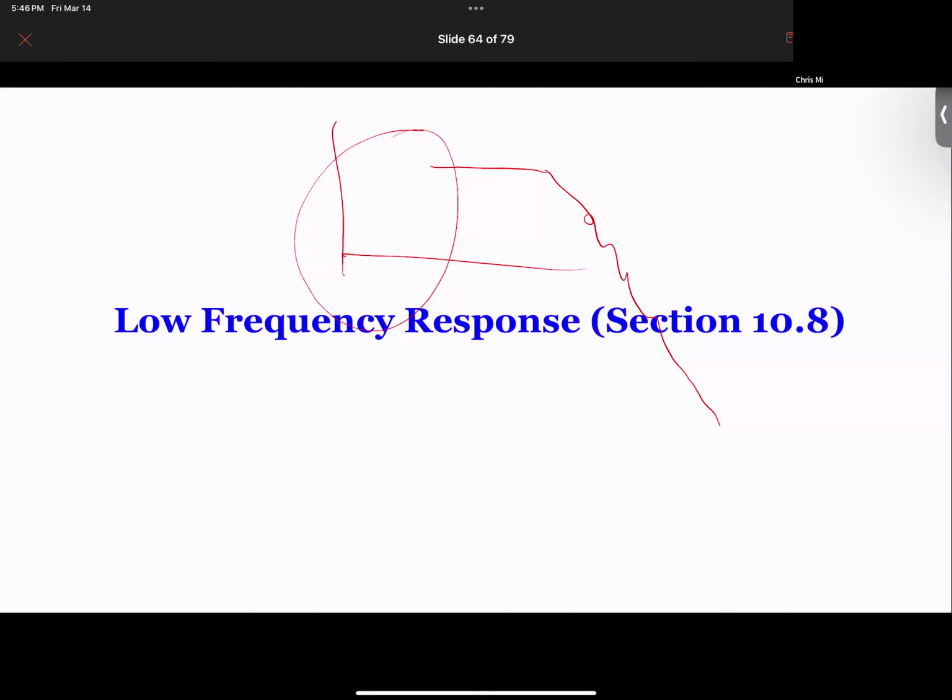For this one, you said it goes down 40 dB because we have 2 poles. Don't we also have a zero? You have a zero, and your zero is probably somewhere over here, far away. We're just assuming the zero is far away. We have 2 poles, so it goes down 40.